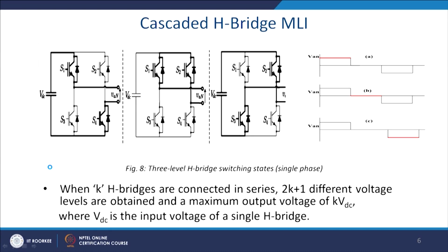Total 4 different switching is possible for these 2 inverters. So, you can get the number of states. So, see how it works. You have these switches, and when S1 and S4 are on, it is a typical conventional single phase H-bridge inverter, so you get VAN,